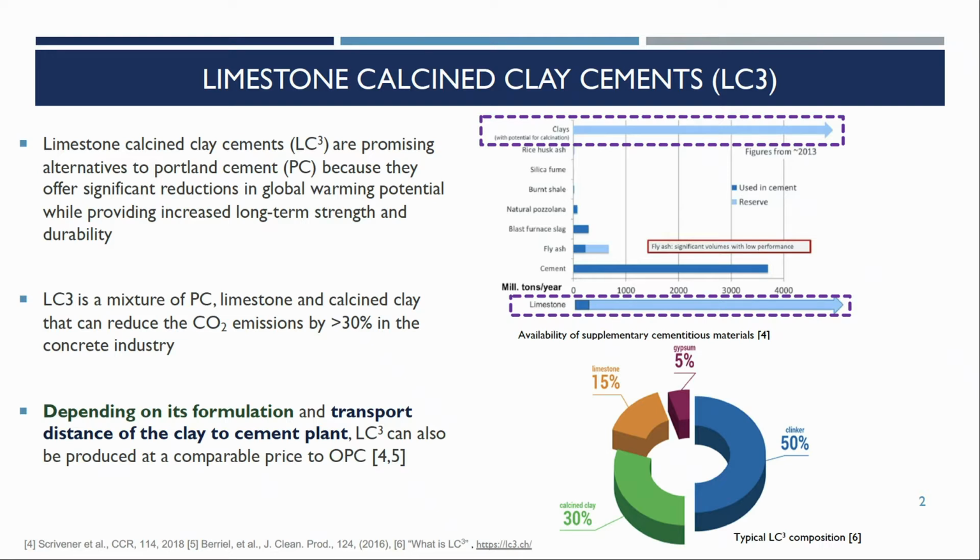The main challenge, though, is that the flow of the paste is significantly curtailed, particularly through the effects of the clay. The more clay, the higher the yield stress and the higher the plastic viscosity. And so we were interested in developing a model, mostly for starters just understanding the basis for this.